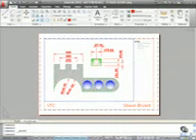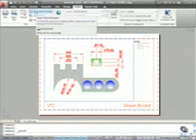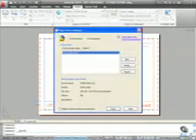However, if I right click on that tab or go to my output tab here on the ribbon, I can start looking at the page setup here. So let's go to the Page Setup Manager. I can click here in the plot panel and go to Page Setup Manager, or if you use the tabs, right click Page Setup Manager there as well.